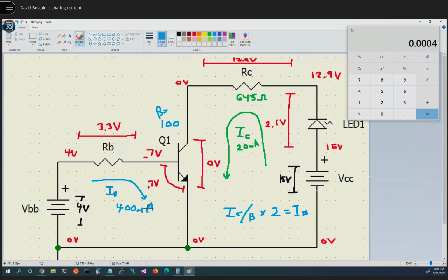So see the big gain we get here? This is very small, and yet we're able to drive a circuit. This could be a motor. This could be something more potent, and we could drive bigger circuits over here with very little current. So our chip, which is supplying, it's not really a battery, it's a pin on a chip that's either 0 or 1, 0 or 5 volts, is able to produce this current or not produce it, turning it on or turning it off. Works kind of like a relay if you've ever worked with mechanical relays.